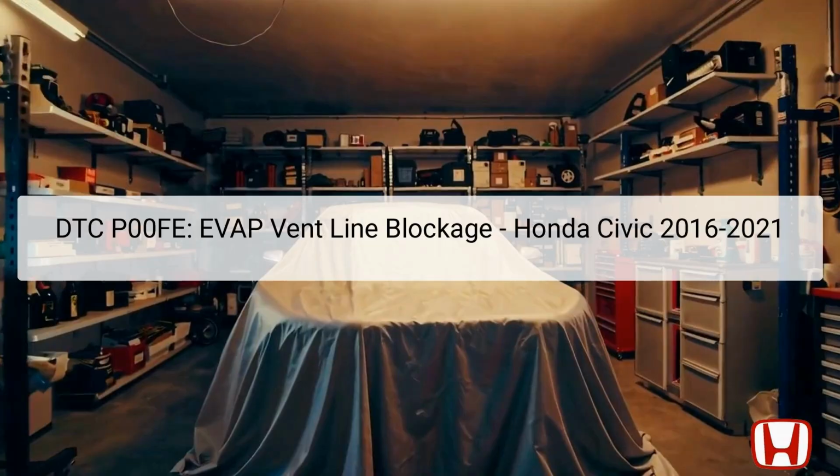DTC P00FE indicates a fuel vapor emission system vent line blockage, impacting the vehicle's fuel system. The EVAP, Evaporative Emission Control System, has components designed to prevent fuel vapors from escaping into the atmosphere. The vent line is a critical part of this system. It connects the fuel tank to the EVAP canister, allowing for proper venting.